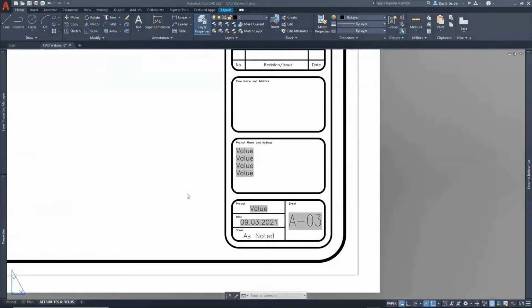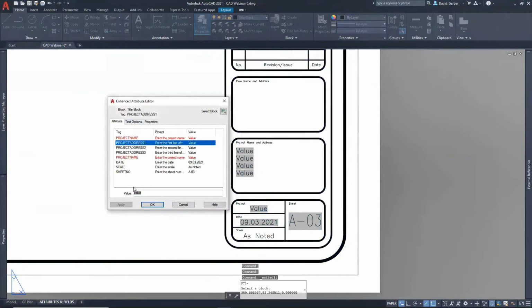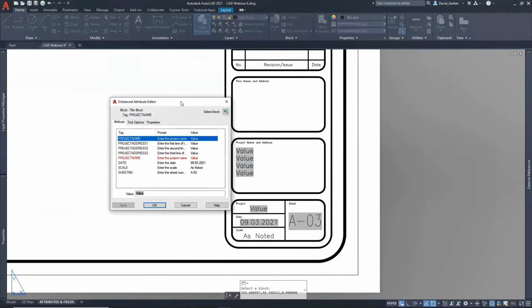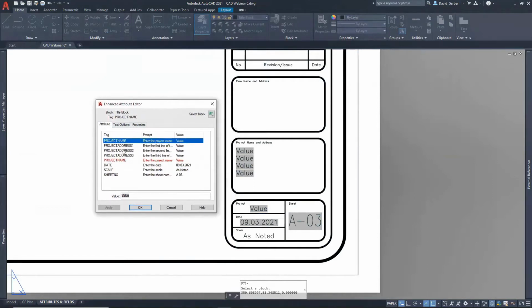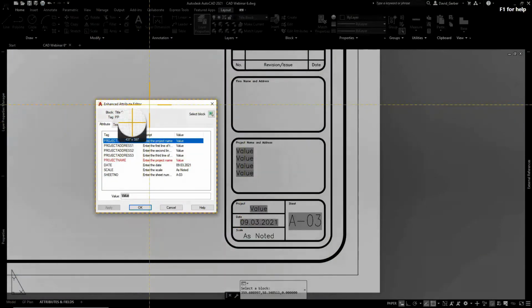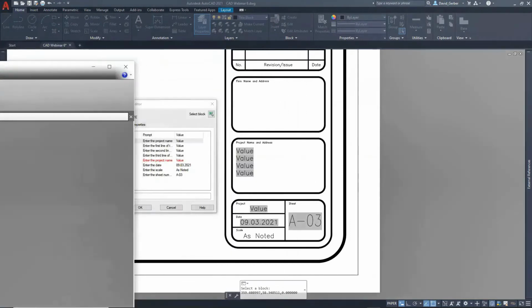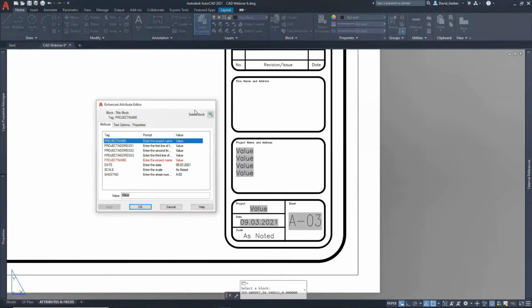Within CAD, we're going to play around with those title block fields that we saw before. So you can see the tags that we have just from before, and it is very picky. So just make sure you note down what the custom parameters are if you've created them yourself, or I usually just take a screenshot. I quickly take a screenshot and have it off to the side while I'm building my sheet set manager. And then eventually you won't have to worry about them. It's just the first time when you're setting it up.